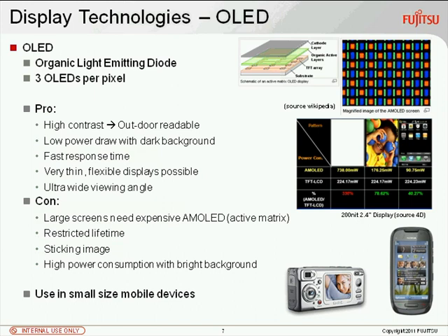Let's start with this. LED is clear, it's light emitting diode, and the O in front is for organic. Why organic? Because the layer where it's put on is organic material. This is from the production process. So there is a plate where it's mounted on, then there is the TFT array, then there is the organic layer which includes the LEDs, and then there is the cathode layer for the other pole of the voltage.